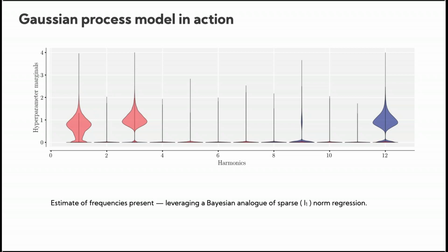It's a similar idea here, where we want to best characterize the circumferential variation in temperature, which is inherently sinusoidal, but to explain that sinusoid, which usually comprises multiple modes and noise, we want to use the fewest number of modes possible.